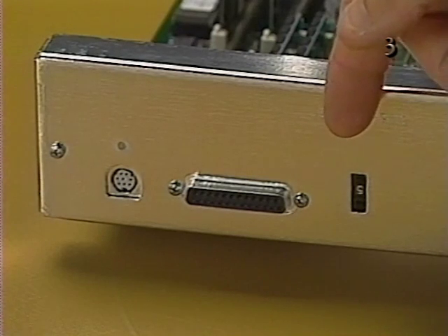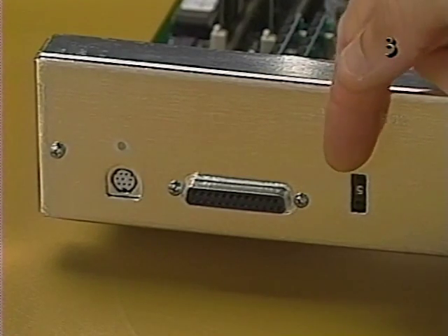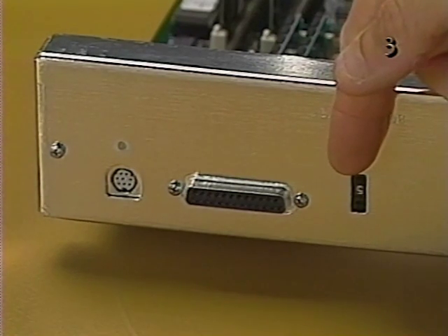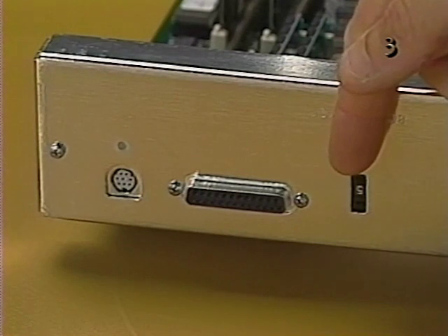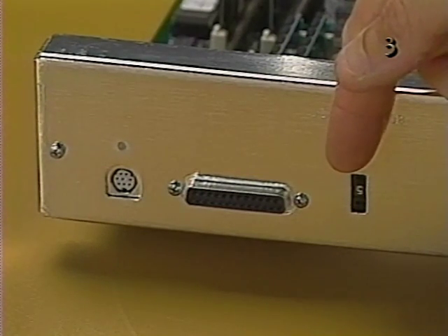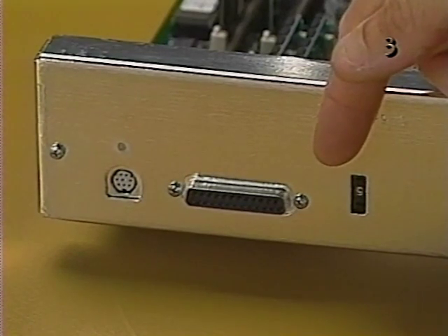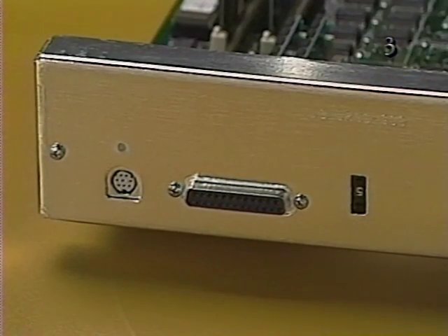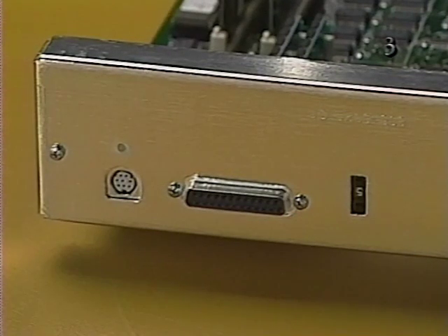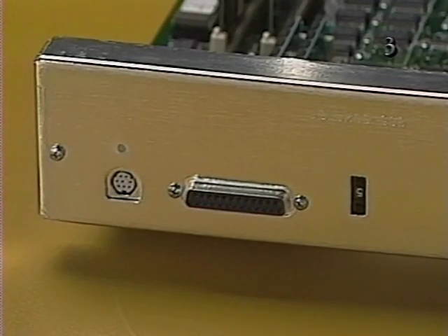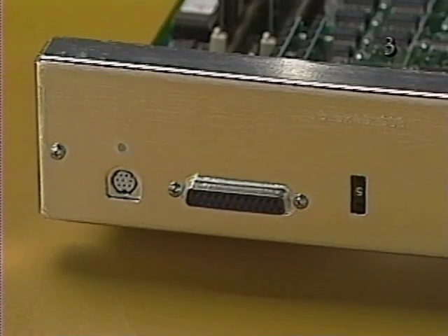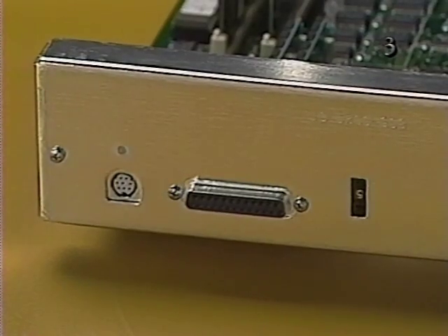Finally, the Personal LaserWriter NT dip switch pinwheel. This pinwheel is identical to pinwheels used on SCSI devices to give the device an identification number. The pinwheel has the numbers 0 to 7. Each number corresponds to one of 8 possible dip switch settings. As with other types of dip switches, the printer must be powered off, then on again, for the I/O board to accept the new setting.